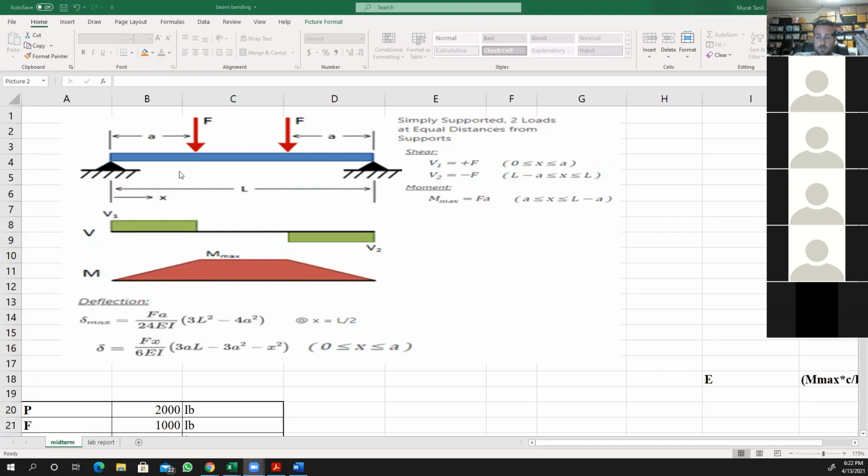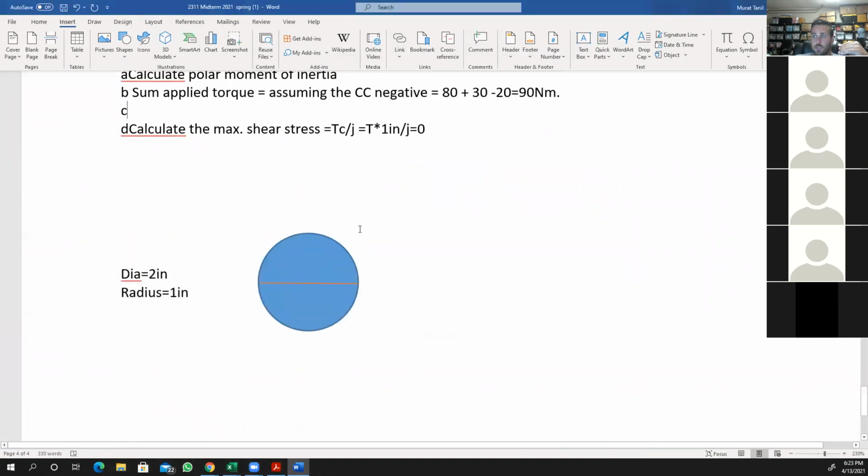It's the same beam over here. Imagine this beam is cut from the center, and the only support is on the left end, a pin support. And I'm applying force with my finger. It is trying to rotate clockwise. And there is also an internal, exactly opposite force and moment that resists the external force, correct? Otherwise the beam will keep rotating. That's the whole point. Torque and moment are the same thing. It's just that the orientation is different for a beam and a circular shaft. And over here, the force is applied in this direction. Let's make it more clear.